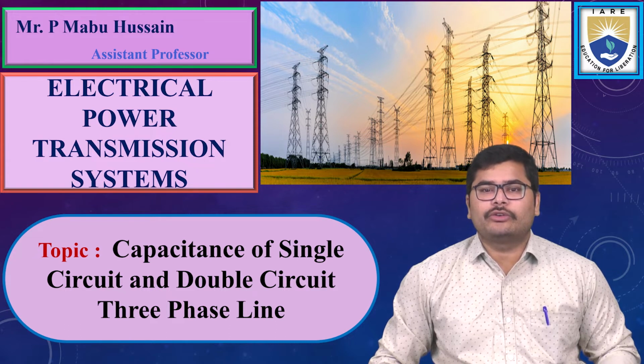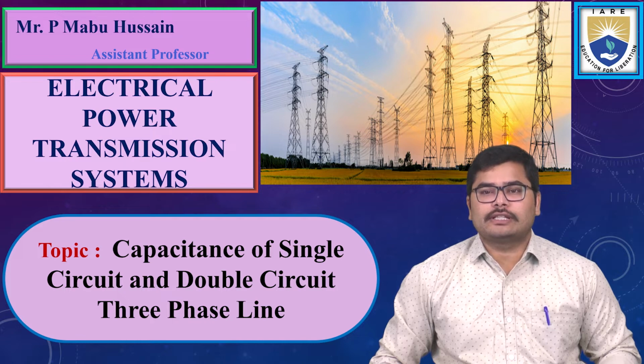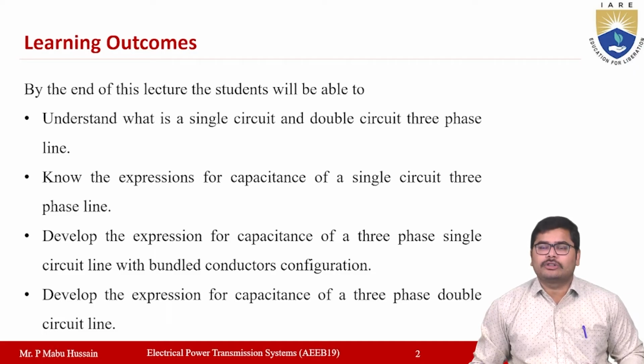Today, in this video, we are going to discuss the capacitance of single circuit and double circuit three-phase transmission lines. If you observe the learning outcomes of this lecture, by the end of this lecture, the students will be able to understand what a single circuit transmission line is, as well as what a double circuit transmission line is. They will also know the expression of capacitance for a single-phase three-phase transmission line, and also develop the expression for capacitance of a three-phase line having a bundled conductor configuration, and also develop the expression for a double circuit three-phase transmission line.